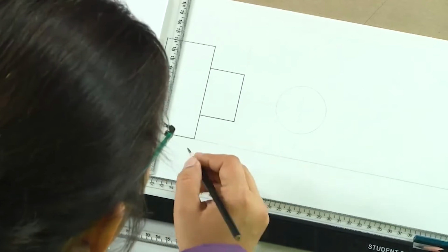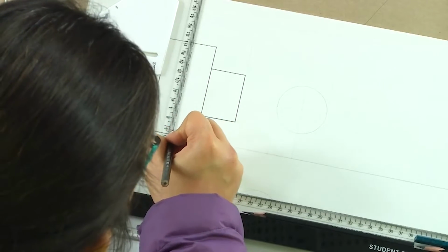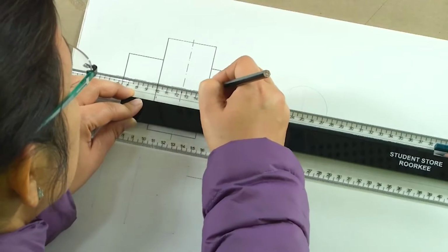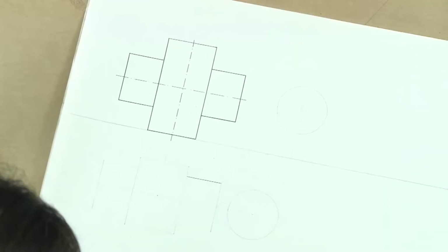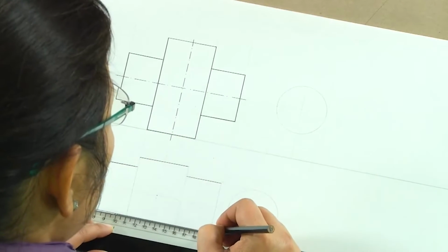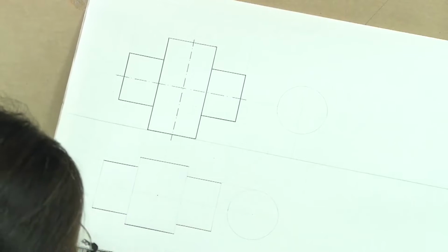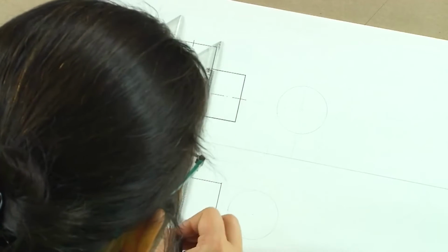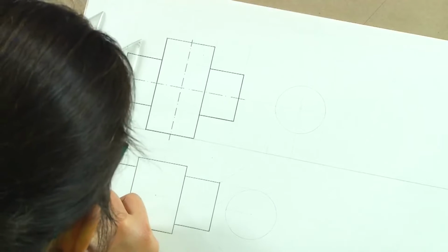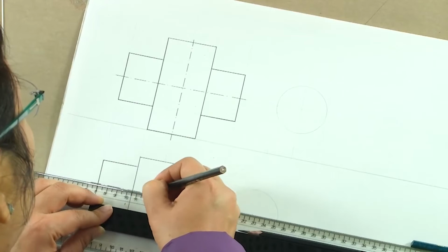In top, I will also make the axis as we see. So, this axis we are seeing being perpendicular to HP and parallel to VP, that is for the prism. I would advise that you should make the axis all the time, because drawing the axis helps you understand how the solids are being placed. Then in the top view, we will be seeing the base of the prism, and we will again be seeing the cylinder exactly the same as we saw in the front view. So, this is what we see in the top view. Now, here we are not seeing the axis of the prism, but we will be seeing the axis of the cylinder, because it is parallel to both HP and VP.